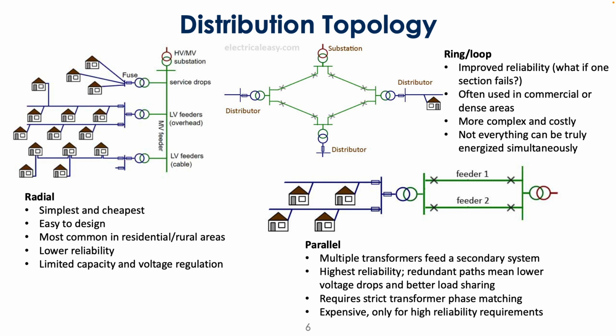And in order to get them in sync, you need to transform your AC into DC and back into AC to have what's called a DC tie. And all of that has to do with this phase question of making sure that the waveforms are in sync.